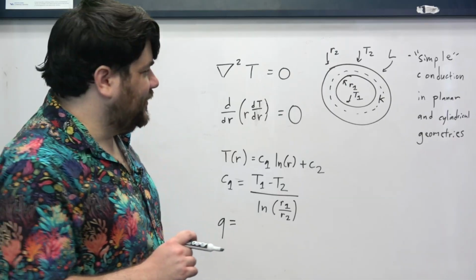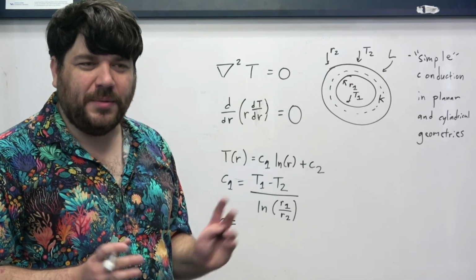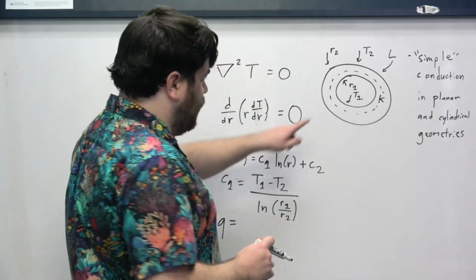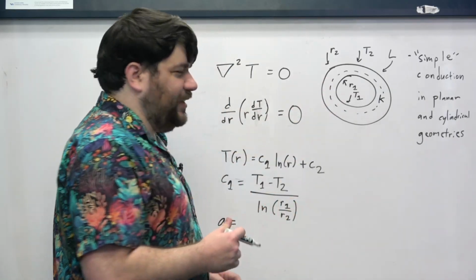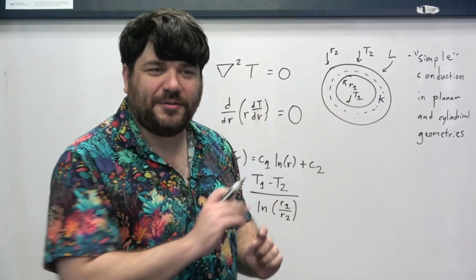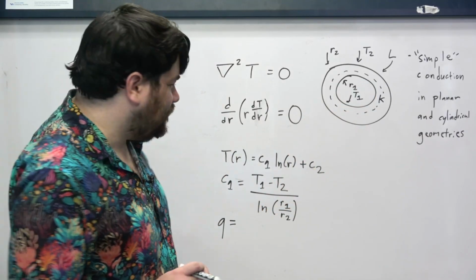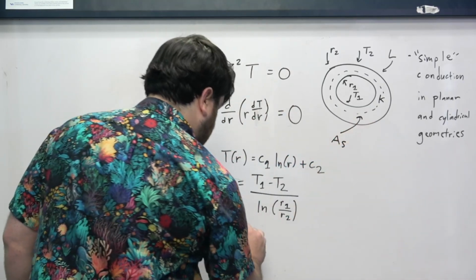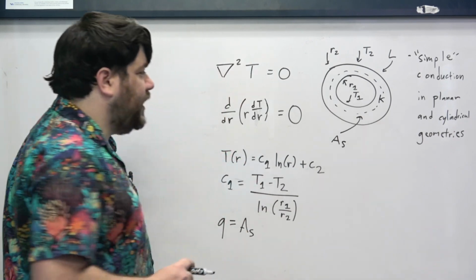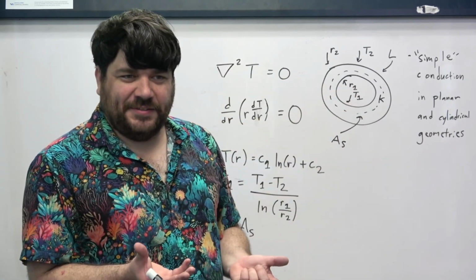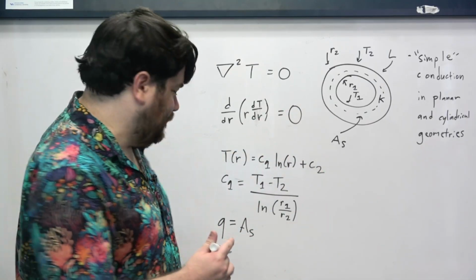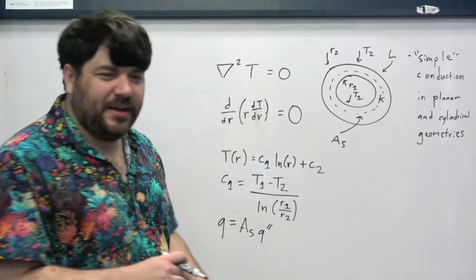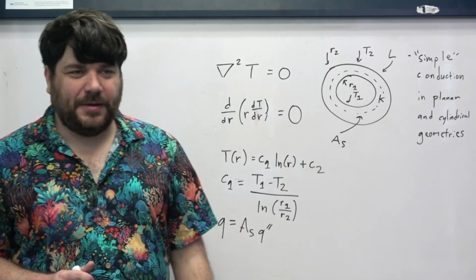But be aware that maybe cross-sectional area is a confusing term. Maybe we should just say, what is the surface area of the thing that we're cutting, right? So the curved surface area, like the surface area of the cylinder that is generated by creating this cut, okay? And this surface area multiplied by whatever the Q double primes are on that cut, on that boundary, assuming that they're uniform, multiplied by the surface area will give us Q.